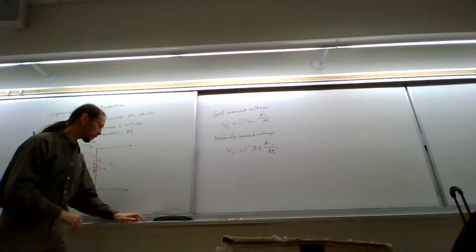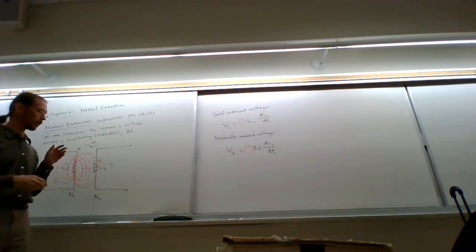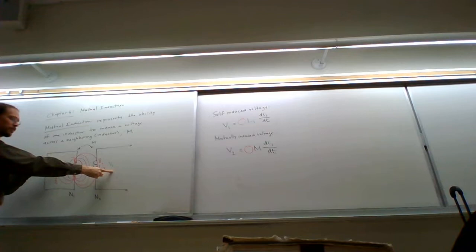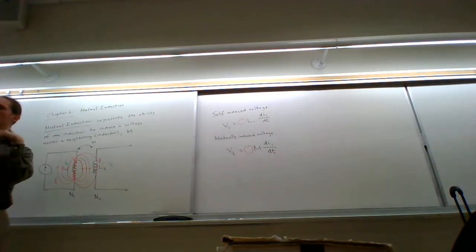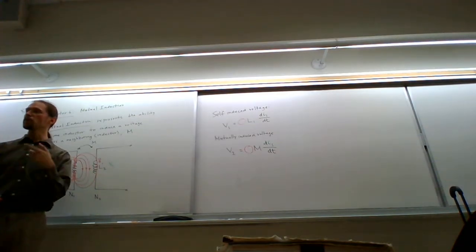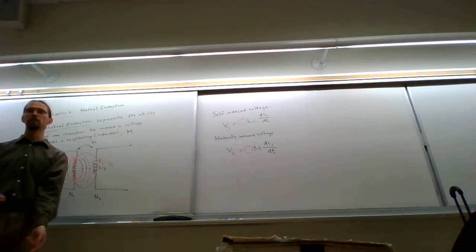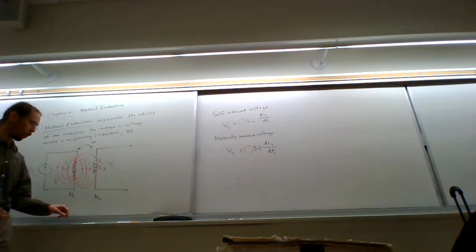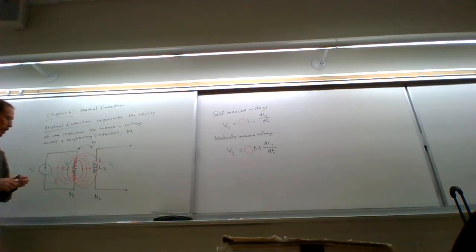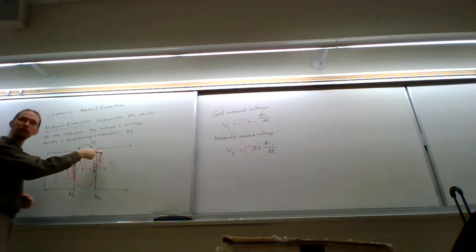Now, very conspicuously, one of the things that I left off from this voltage V1 and this voltage V2, whenever you specify a voltage, you need to specify a magnitude, but what else do you need to specify? You need to specify a polarity, right? So over here, we need to know whether this is plus and this is minus, or this is plus and that is minus, and similarly over here.